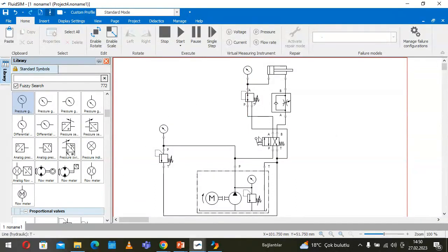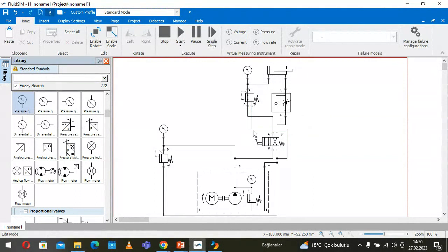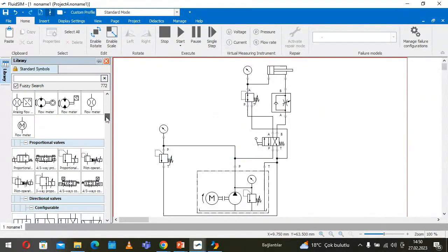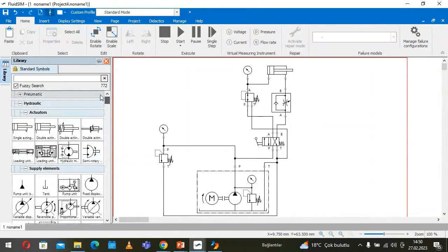And of course, we need another line to open the oil during the return stroke of the piston, the oil has to flow into the tank. So free flowing we need, not via the pressure regulator. So therefore we need a one-way valve. One-way valve. Where is it? Here somewhere.